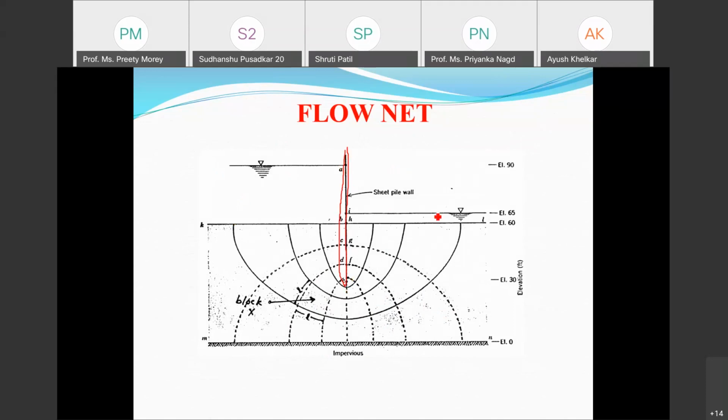Say this is a caisson, used for construction of bridges in a river. They want a dry place here, so they put a steel pipe surrounding the area. The water will be outside, but this area will be dry, so they can excavate and construct the foundation.